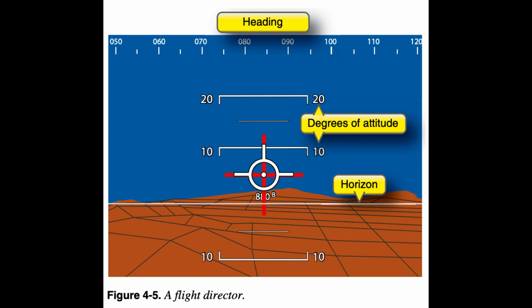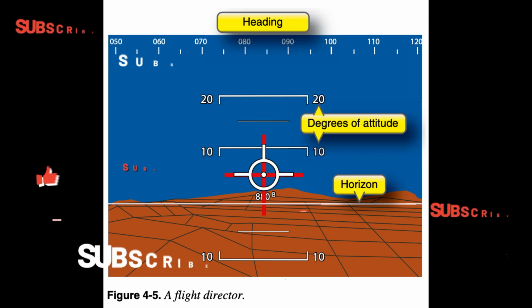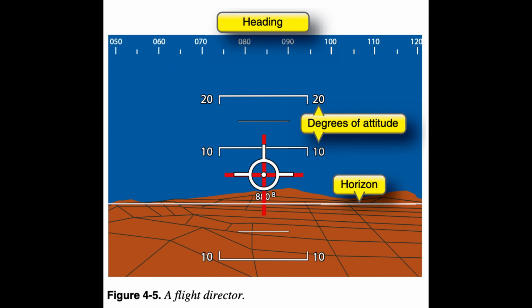The flight director usually receives input from an ADC and a flight data computer. The ADC supplies altitude, airspeed, and temperature data, heading data from magnetic sources such as flux valves, heading selected on the HSI, or PFD/multifunction display, MFD. Electronic Horizontal Situation Indicator, EHSI. Navigation data from FMS, Very High Frequency Omnidirectional Range, VOR/Distance Measuring Equipment, DME. And RNAV sources.